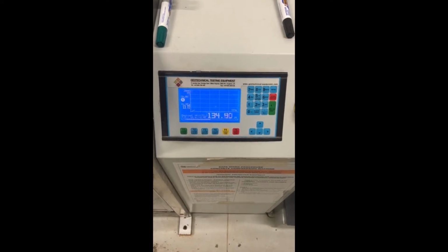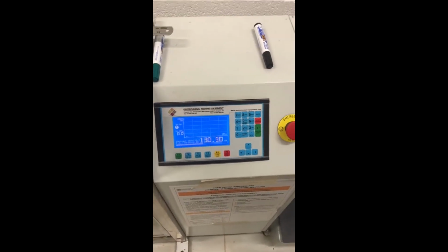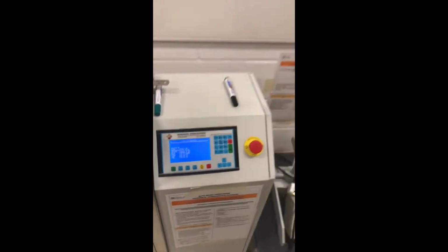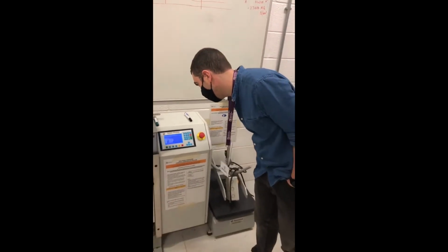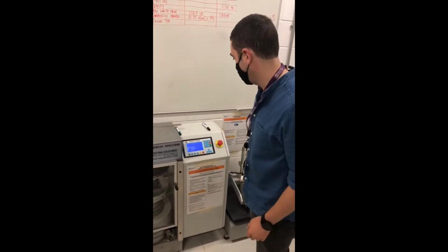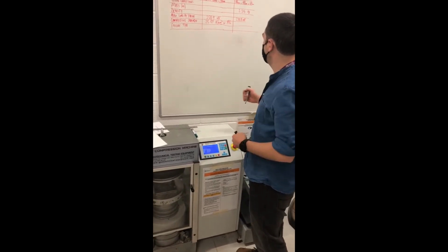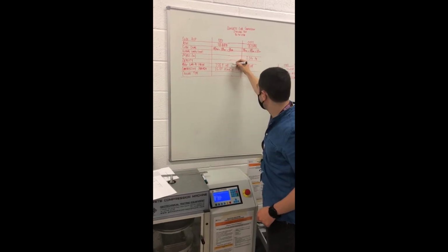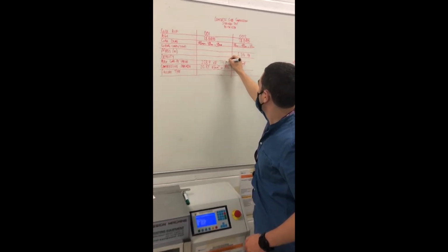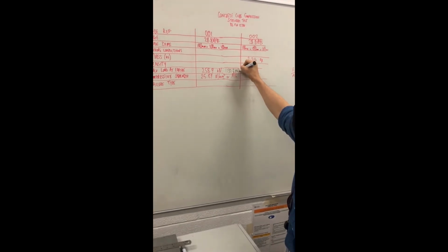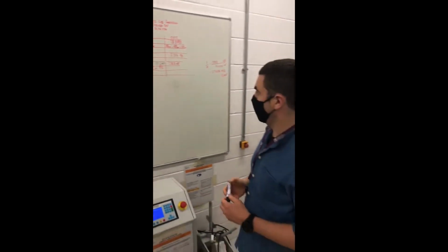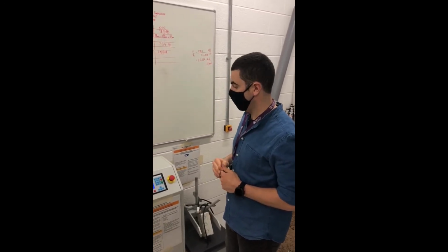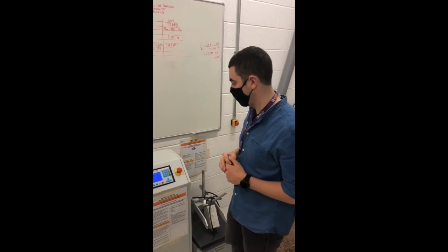Last time we had 258. This time we got 137.2 kilonewtons of failure. So let's put that in brackets here. So just over half is left compared to the initial test we had for that one, the residual strength.